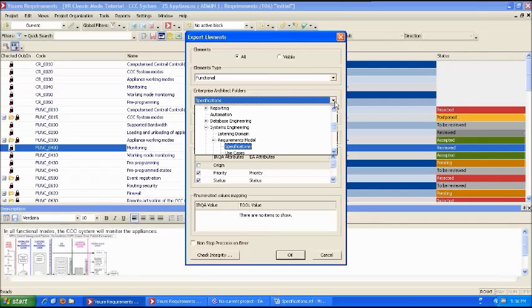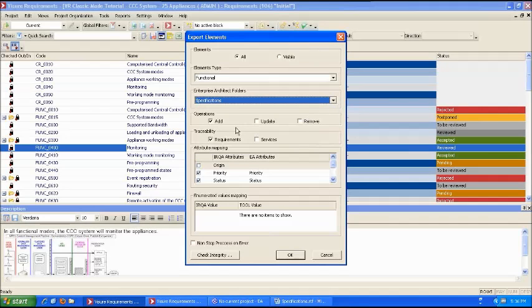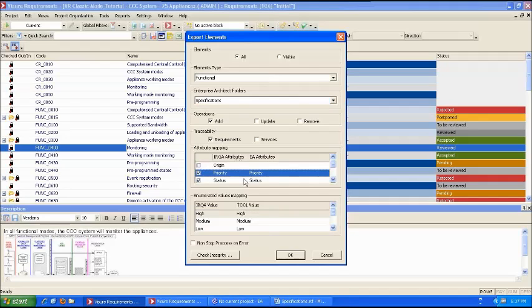just as an example, to write the corresponding use cases in Enterprise Architect to implement them. Another step is to select the package where the requirements will be exported. Take into account that this export process can be used not just for a first import, but also for updating requirements in Enterprise Architect as we publish new versions of the specification. And we can also include the traceability. We are also able to export custom attributes, and we could even enter a value mapping for enumerative attributes.